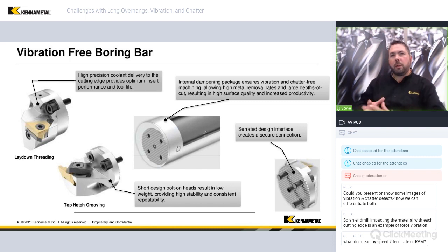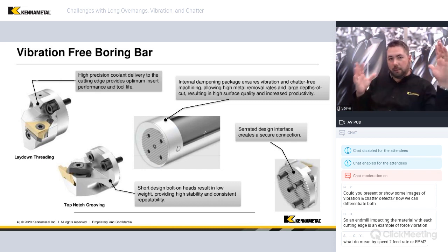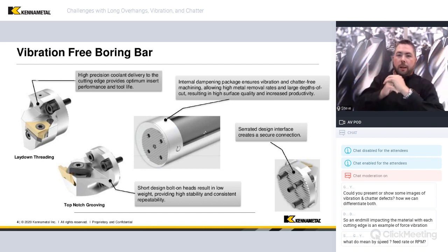One of the biggest things that I want to get across to people in terms of using any tool that you're doing vibration analysis on, or a plug-and-play solution like this, is that you have to be repeatable. If you're going to do any type of tuning, for instance, using a tap test or any type of prediction ahead of time, you need to guarantee that you put the tool in the machine the same way every time, where it's going to have the same stiffness, damping, and sprung mass. That modal mass has got to be repeatable.